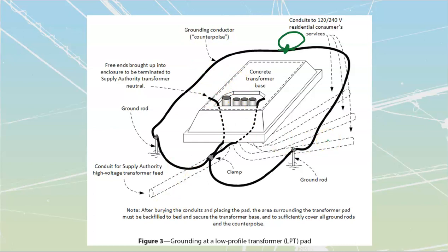All right, lightning protection. We talked a little bit about that. The lightning rods that we're going to place on top of tall buildings are a purposeful way that we are going to divert and run anything that is discharged from the atmosphere down and through there. We do want to keep those lightning conductors away from other components because otherwise it will jump over. 300 volt insulation on NMD90 is nothing to that lightning strike. It will easily move across there.